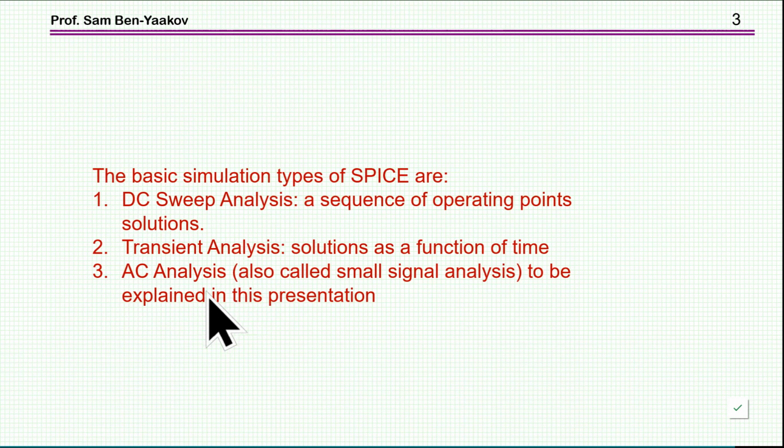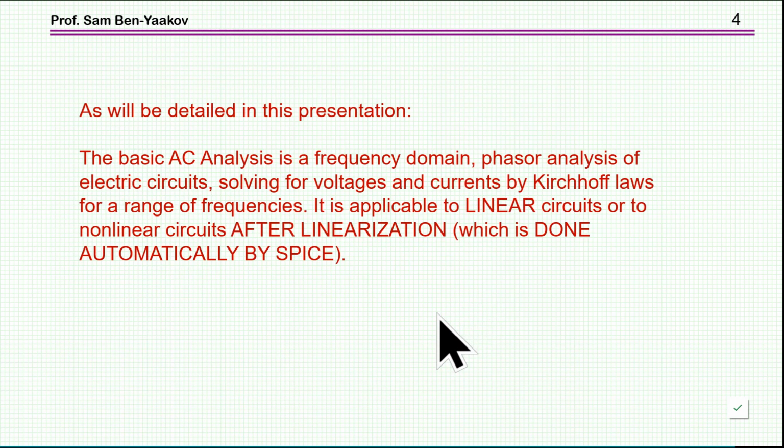Now, AC analysis, which is also called small signal analysis, is what we are going to discuss in this presentation. As I'll discuss in more detail later, let me just summarize here at the beginning that the basic AC analysis is a frequency domain phasor analysis, that is j omega, etc., as we are used to doing in calculation of AC circuits, linear circuits, and it is solving for voltages and currents by Kirchhoff's law.